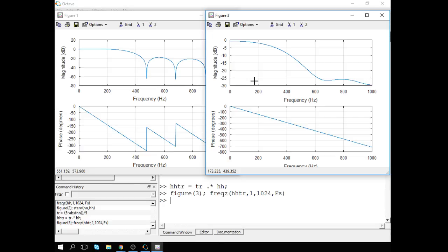The next trick, the last trick we can possibly do here, is to do something for the transition bandwidth that we just messed around with. There we use the well-known fact that multiplication in time space is the same as division in frequency space. Kind of, more or less straightforward. If you multiply in time, you are squeezing the frequency space. Wider here means narrower here.